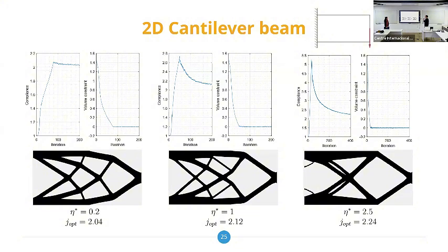If we think the best solution is always the one that gives you the minimum compliance, because it's the one with more stiffness, in this case it is the first one, the one with 2 points. The more classical one, that you would expect.